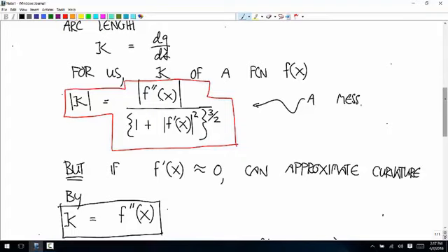For most of this class, we've been assuming that deformations are small, like small enough that the strains are pretty small. But if you have a single beam, well, let's think about this sheet of paper. Right now, every point on this piece of paper has a small strain, but the slope of this paper is not small, and we wouldn't be able to make this assumption.